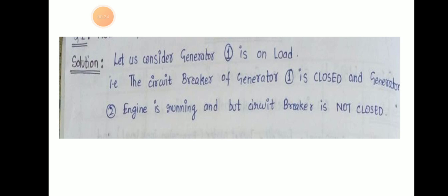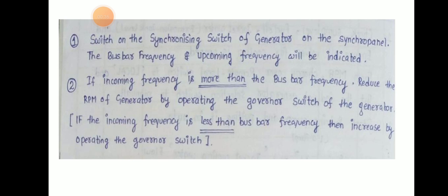This is the condition. So we have to switch on the synchronization switch of the generator on the synchronous panel. Then we can see the bus bar frequency and the incoming frequency indicated.